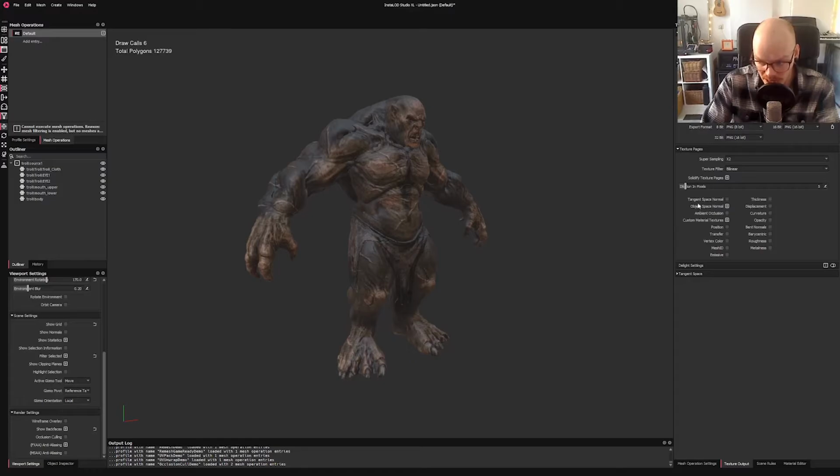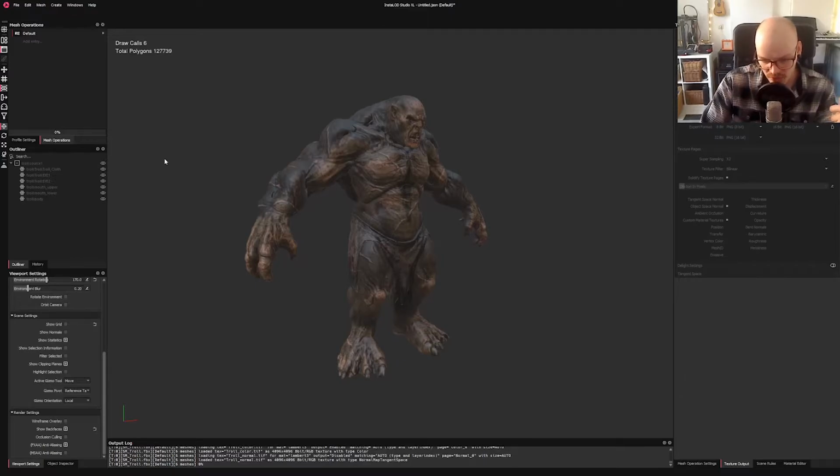So in my case, we are going to bake everything down onto a single 2K texture. We're going to bake the normal map and the color texture. So with that done, we're going to take the entire scene. We're going to click start and let it process. So from 130,000 polygons, generating a new reconstructed mesh, new UVs, and baking all of those different textures together.